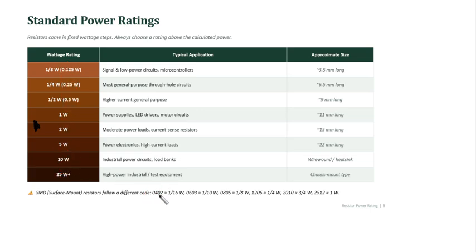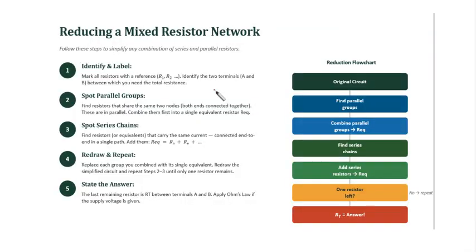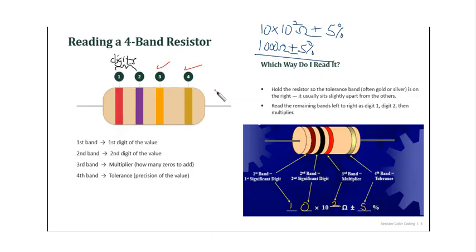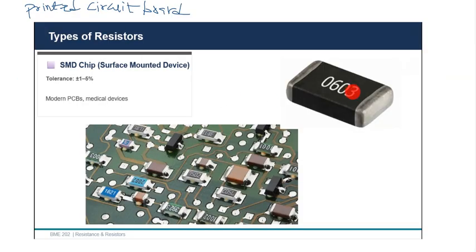You are going to see a number on it. You might not be dealing with much of the SMD resistors at this beginner level, but you're going to see a code on it. That code tells you what the power is. Just like in a very previous discussion, we said that the SMD resistor looks something like this. You can see that there's this code on it, 0603. This code tells you the power rating, and it is not expected that you try to memorize this power rating based on this number. If not, you are going to have to memorize a lot of numbers against power ratings to be able to tell what the power rating of a particular SMD resistor is.